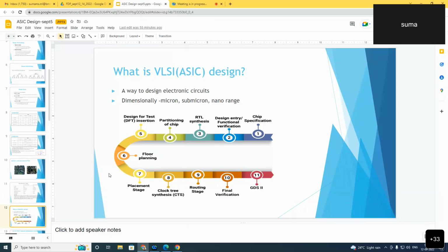of a MOS transistor. And while manufacturing any die, I think on Wednesday we'll be showing you the wafers. We will see the dies in the center will be pretty accurate in the process value, but the ones lying in the periphery will tend to deviate from the values. The deviation is not that big, but it can have a significant impact on the timing also. So we will see all this on Wednesday, face to face, what these wafers are and what these unfinished dies are.